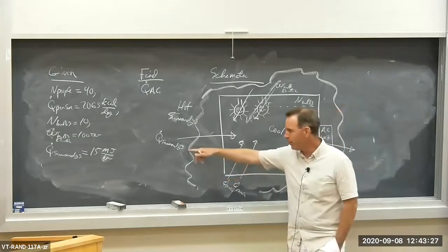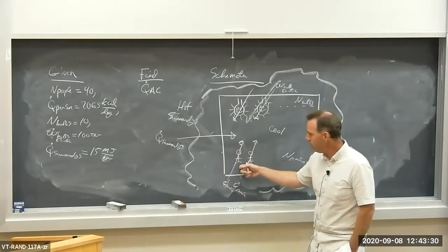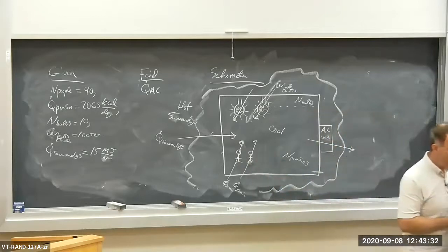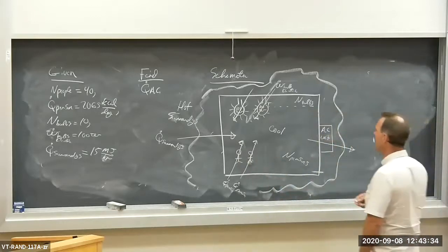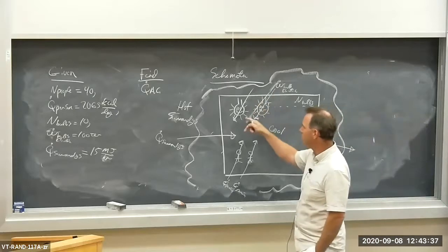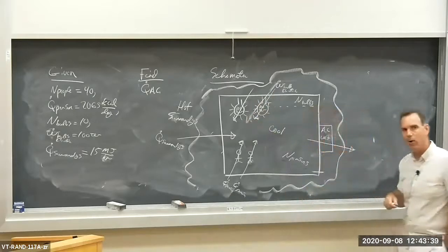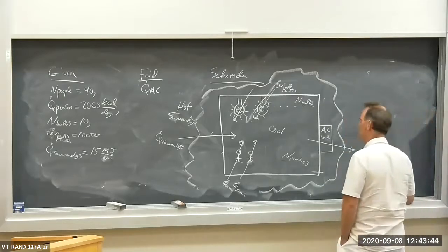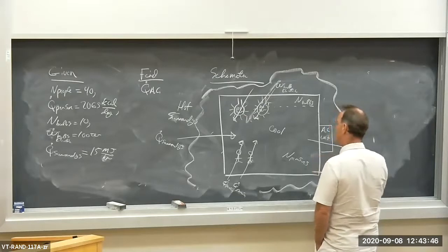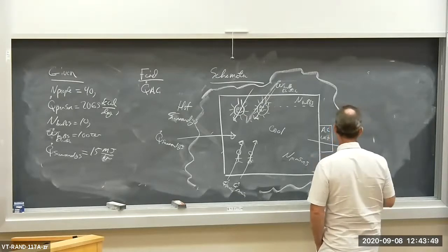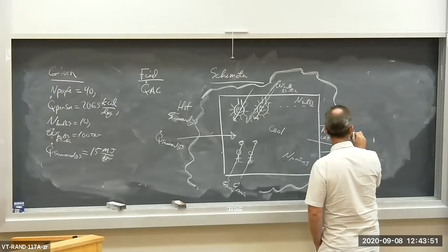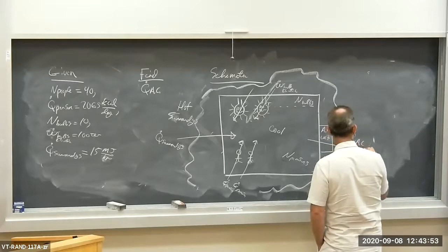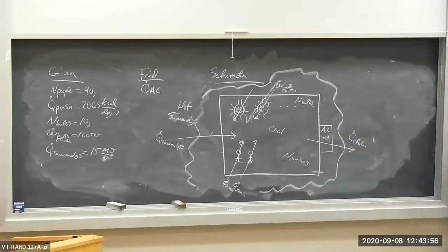The heat transfer from the environment, the heat transfer due to metabolism from the people, so the body heat being rejected, and then the energy transfer, the work transfer from electric work or power to running the light bulb. So there are all these things that are adding energy to the room, and we need to suck that energy out or remove it using an air conditioning unit. So Q dot AC is being rejected or extracted due to the use of an air conditioning unit.